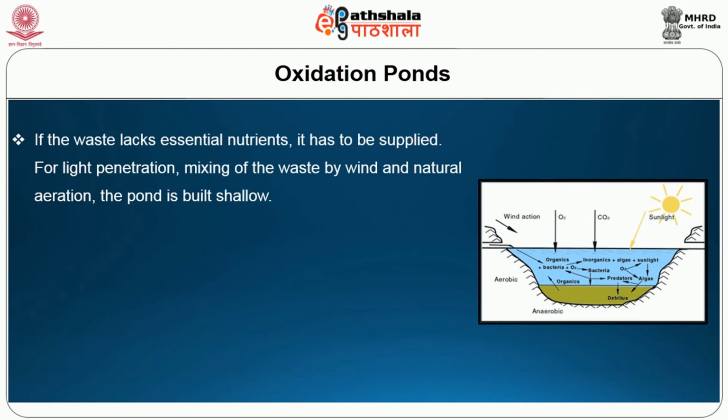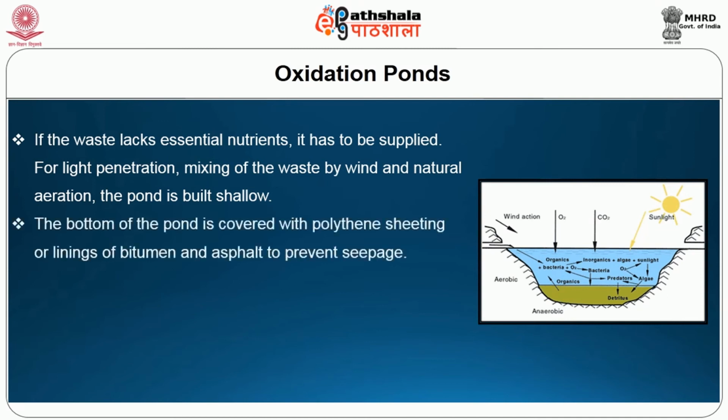For light penetration, mixing of the waste by wind and natural aeration, the pond is built shallow. The bottom of the pond is covered with polythene sheeting or linings of bitumen and asphalt to prevent seepage.